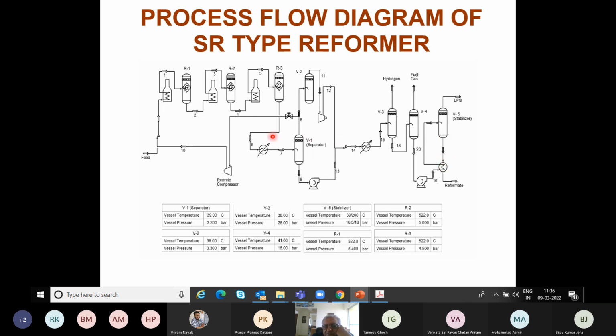So I'll just go through this flow sheet once more. After the reactor, the reactor effluent we cool down, and we recover all the hydrogen and the lighter components, and they are compressed again along with the bottom into a separator where the hydrogen gets separated out, and the rest of it is stripped in order to get rid of any residual hydrogen plus C1, C2. We don't want to lose any C3 components because that is part of the LPG. And so all this is what is called the wild naphtha or wild reformate.